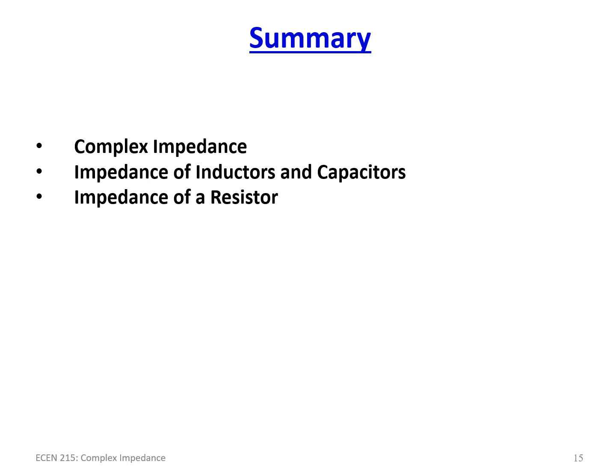So it is in the impedance of the inductor and the capacitor. So inductors being J omega L and capacitors equal to minus J 1 over omega C. So it's important to get those equations memorized. And of course, with a resistor, the impedance is equal to the resistance. It's all real. There is no imaginary part of the impedance for a resistor, versus where an inductor and a capacitor ideally has no real component, but is completely imaginary. So just make sure you learn those equations because you're going to be seeing and using those equations a lot in the upcoming lectures.